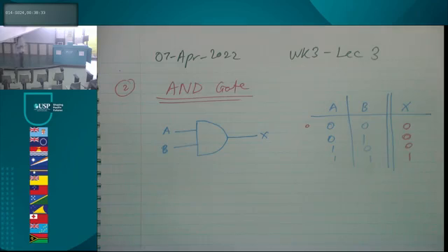In this particular situation, if both sensors are giving 0, that means both are below 26, which means it's cool. If one sensor is saying hot and one sensor is saying cold, remember it's always up to the designer how they want to configure the system. In this design, you need both sensors to trigger in order for the air conditioning to turn on.